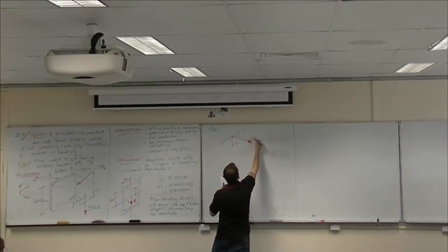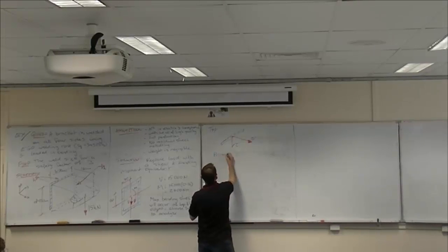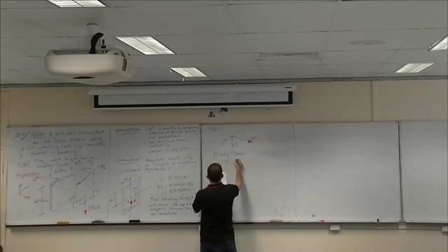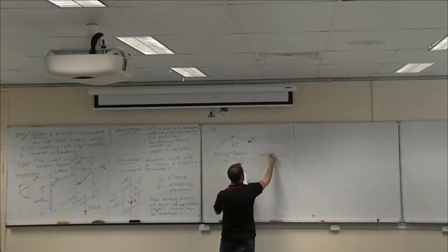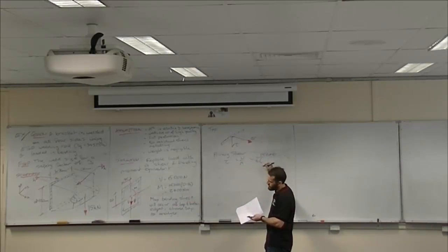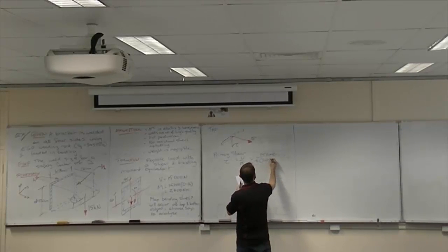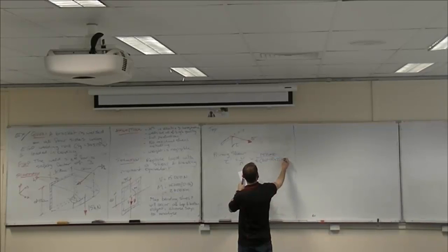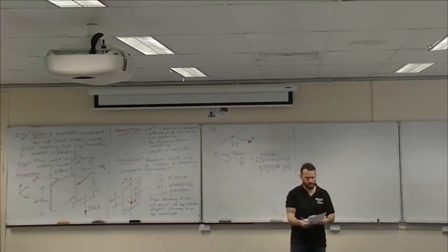Alright, so that's a primary shear and that's a bending stress. Primary shear equals V on A, which equals 15,000 on t times the area. What's the area of our total weld? It's just the total length, yeah. So 2 times 70 plus 2 times 120. 2 times 0.07 plus 2 times 0.12. And I get 39473.68 on t, and I always write my pascals next to it so that when I get to the end I don't accidentally equate that to a megapascal.